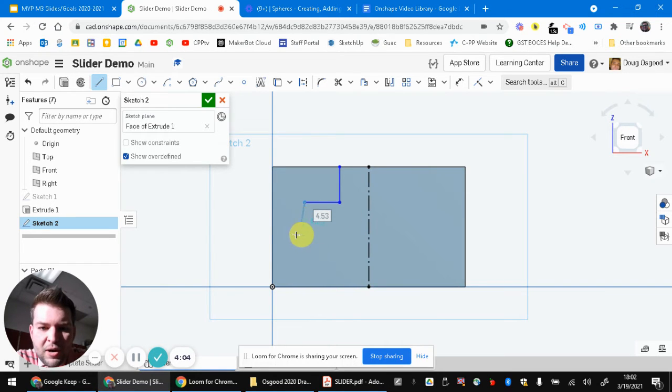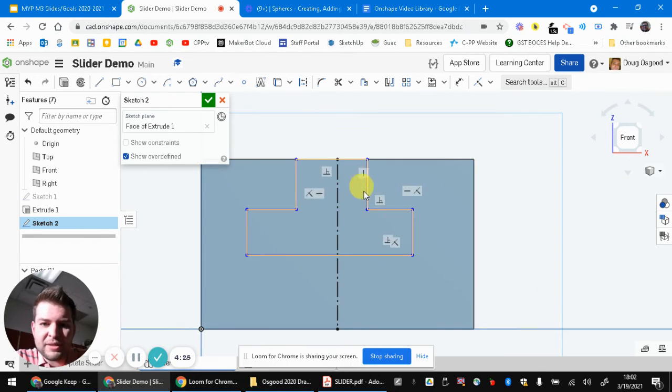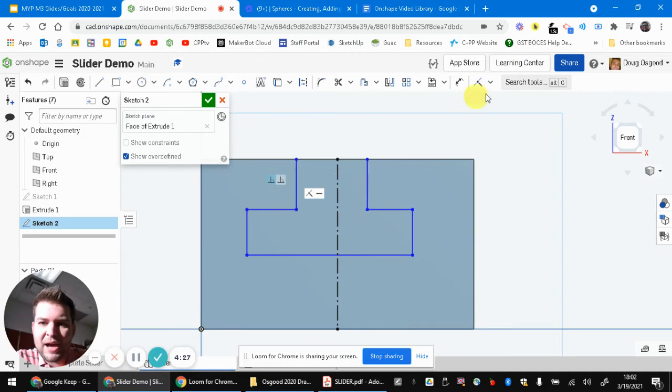And I'm going to make sure, see that dotted yellow line there, that I'm snapping these to be horizontal and vertical. When I get to this point, I'm going to go over here before I click. I'm going to make sure that lights up, and I'm going to move away to get it to snap to be lined up with that line. And then I'm going to finish it out here. Okay. All right. Now, what I can do next is I can center everything on this line.